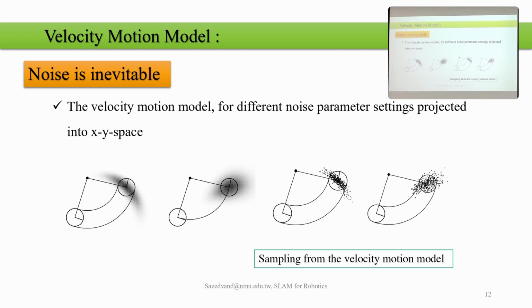That error is also well explained in the book that you can study. And we also discussed multiple times, the robot starts from this bearing, rotates to go there at the velocity, then the error can look like this, can look like this. And we are sampling from those errors, because there are an infinite number of points in the probability distribution, so we can sample those to have an error like that.